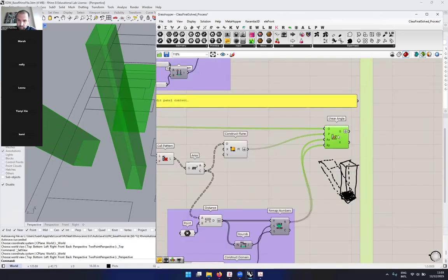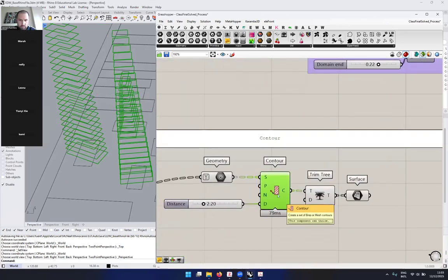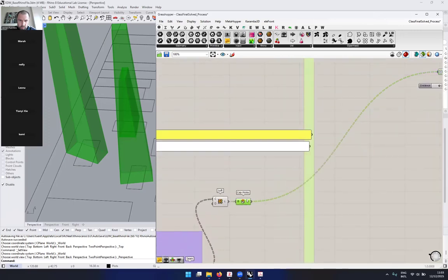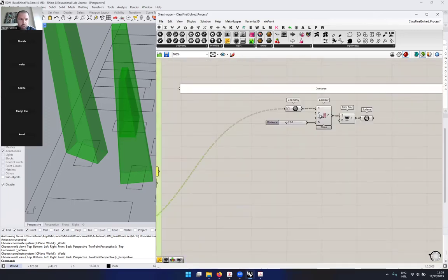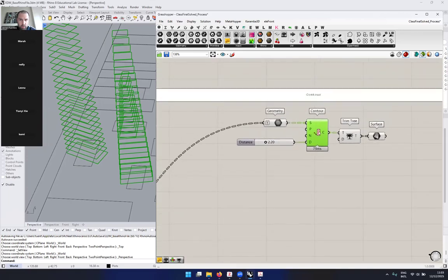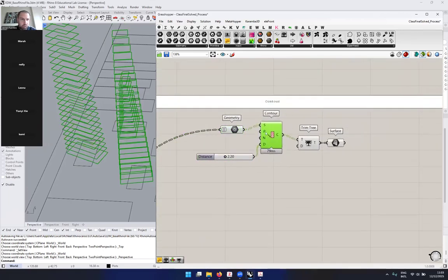My surface command goes red if I connect it to the geometries we did last week, but if I connect it to the ones we did today, there's no error. You mean your contour? The data conversion failed from curve to surface. Yeah, of course. Is contour, Leona, the one that is in red?